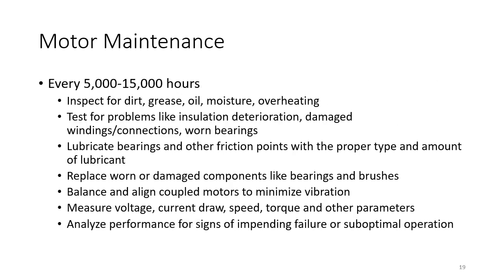Now, I mentioned that AC motors are generally very reliable and don't need much maintenance. There is some standard maintenance which is required. Every 5,000 to 15,000 hours, you're recommended to inspect for dirt, grease, oil, moisture and overheating. When the motor's down, you can also test for problems like insulation deterioration or damaged windings or damaged connections or worn bearings. They can be caused either just through natural wear and tear, but also if there's a lot of vibration or if there is a harsh atmosphere, that can affect the motor as well.